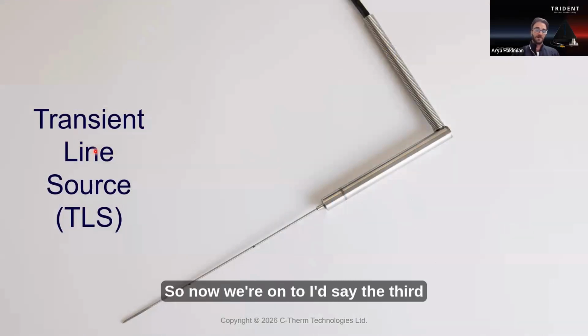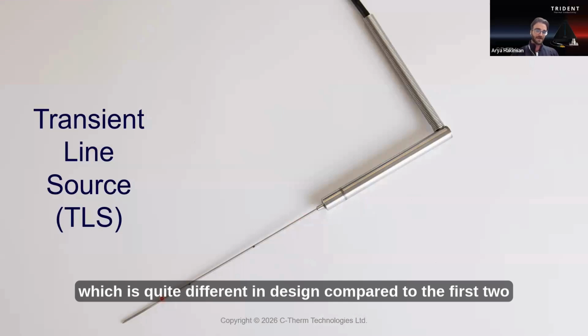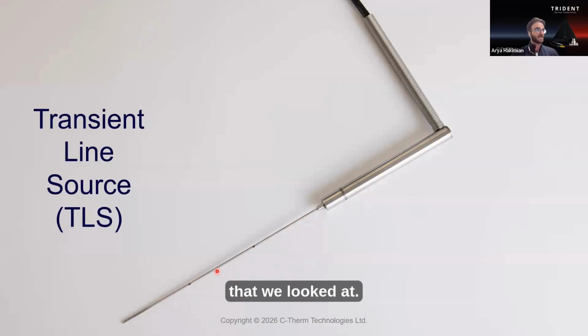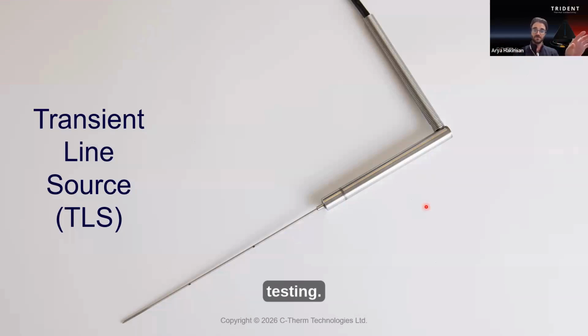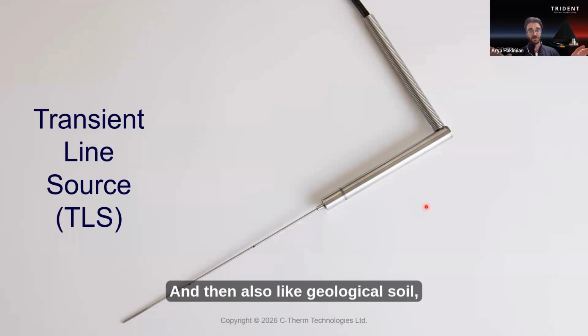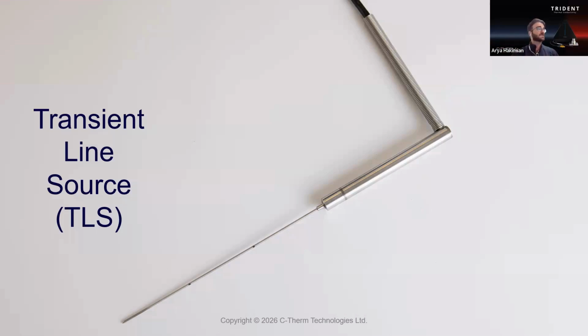TLS. Okay, so now we're on to the third method here, which is quite different in design compared to the first two that we looked at. This is a needle probe style sensor, the transient line source or TLS. You'll see it applied in a few different areas, typically for polymers testing, and then also geological, soil, soft rocks, and aggregates. There's two ASTMs that it conforms to in those two different sectors.